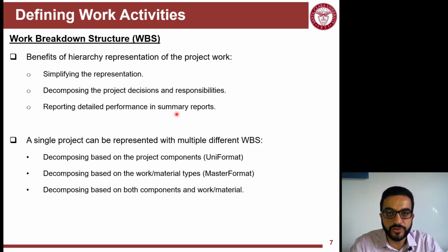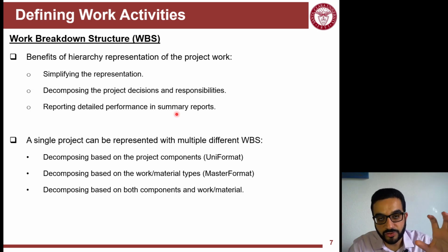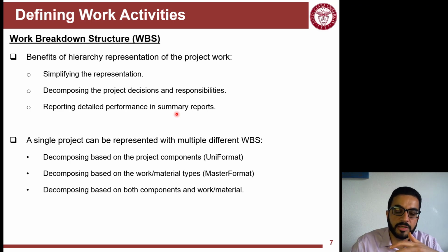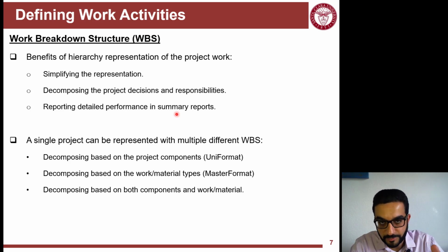So I can decompose the project by project components. When you start breaking down the project, I can break it down by substructure, superstructure, and then you keep going down component by component. Or I can do it by the work materials type. So you're following the MasterFormat way instead of the UniFormat approach.